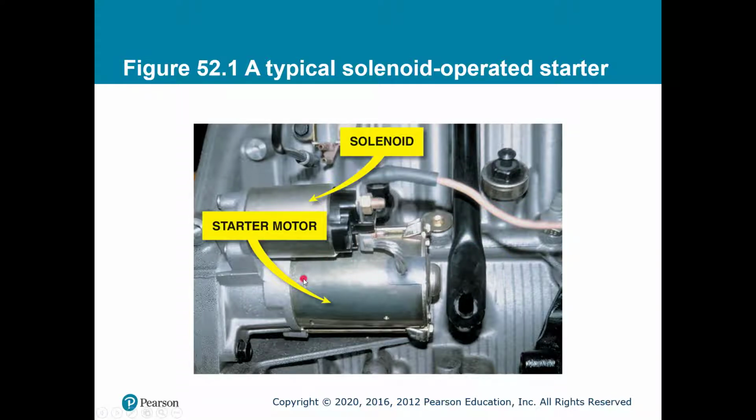Now, what you can see pretty well is the BAT terminal, or B nut, that has steady power from the battery, right? Notice that's a pretty large cable because there's a lot of amperage that has to go over this wire. What we can't see, and it's out of frame, is there's usually a signal wire, which is a small wire. So B for big, S for small.